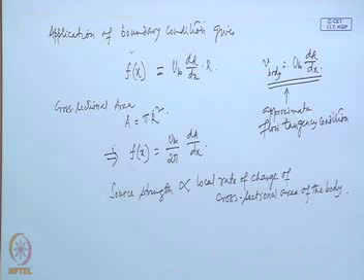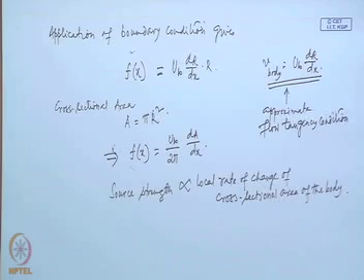Meaning that the portions of the body which are far away from the concerned cross section have no influence on the local condition. That is, flow at any part of the slender body simply depends on the local cross section and its change. The cross sections or the parts of the body that are far away from this station do not have influence on the local flow condition.